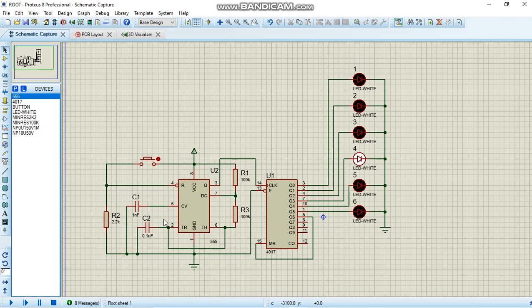We cannot observe the values which change at a faster rate, so there is hardly any possibility of getting the dice biased. The clock pulse is given to the counter cum decoder circuit IC 4017 with the 7 output given to reset. It has 9 possible outputs, out of which the 7 is given to reset, because we only need a count of 6. 1 2 3 4 5 6. So at 7 we reset. We go to 1.